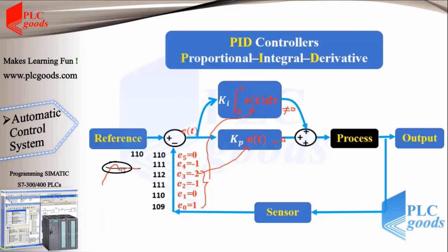In general, in some applications, the weakness of the integrator part can be ignored, but if we want to minimize these fluctuations, we can add the derivative term to the controller.